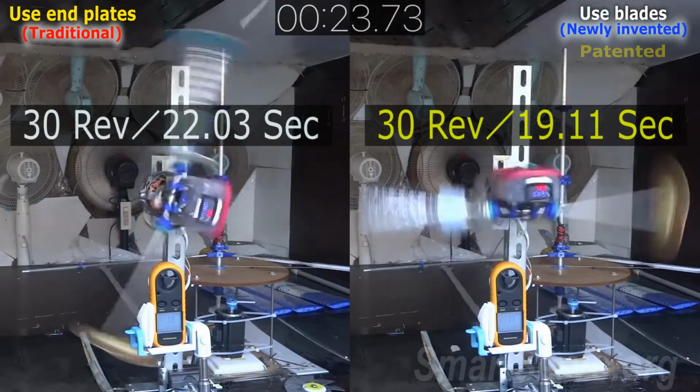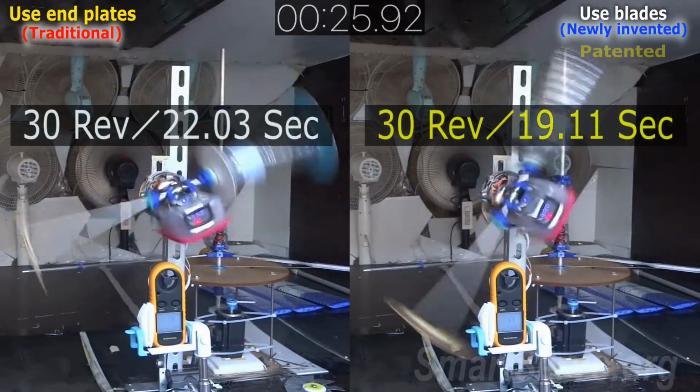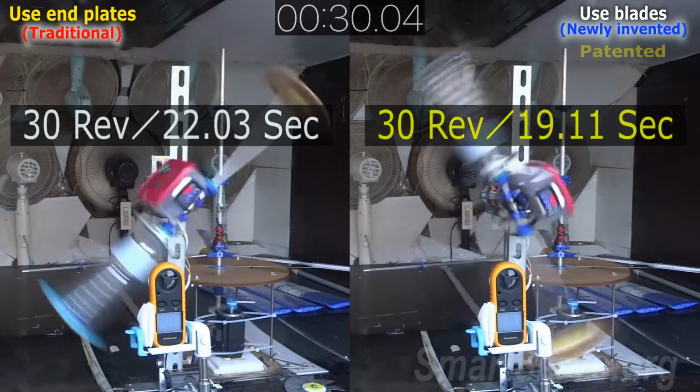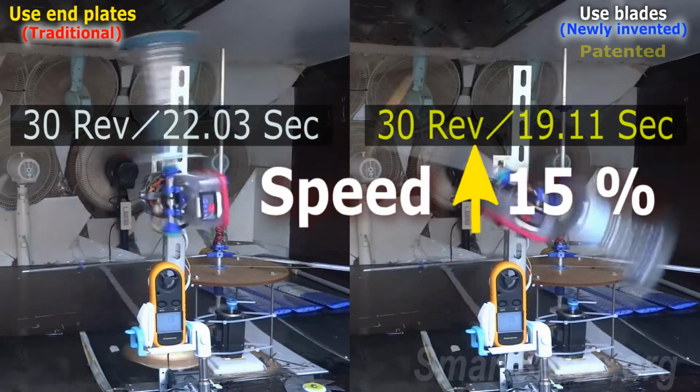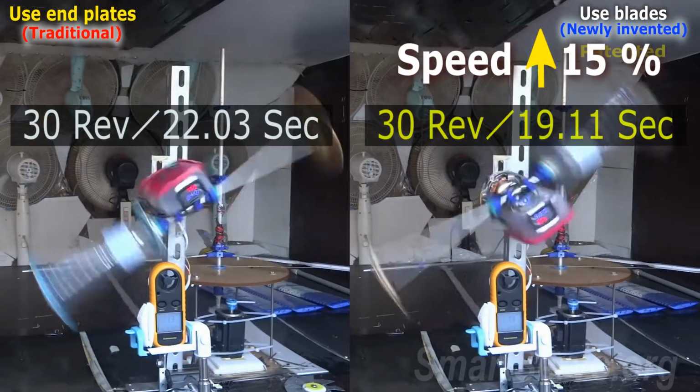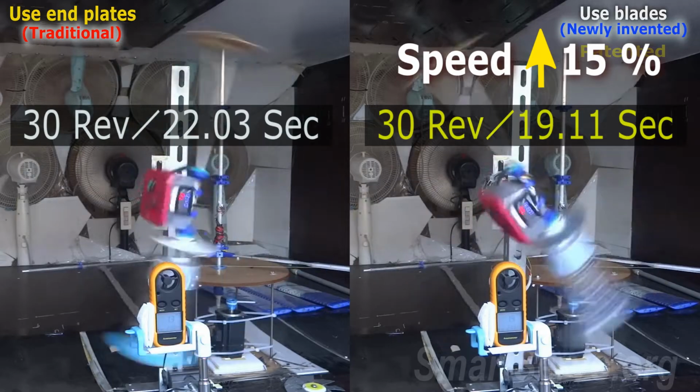It took 22 seconds and 19 seconds from left to right, respectively, indicating that the rotor with blades increases the speed by 15%, which helps to improve the efficiency of the wind turbine.